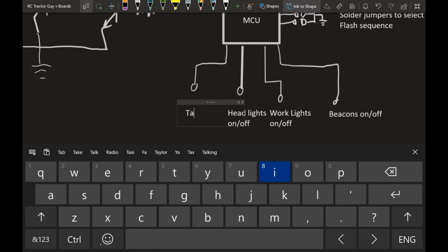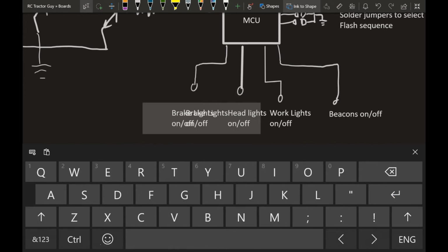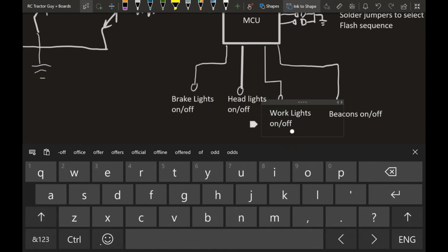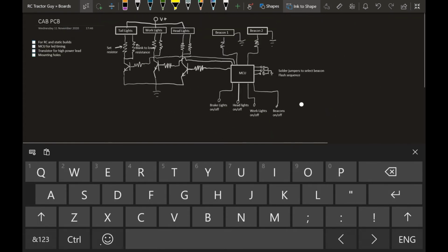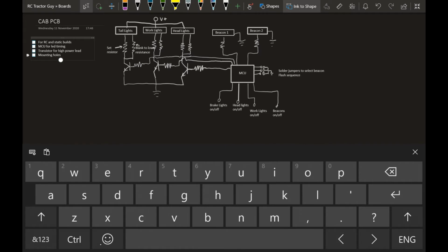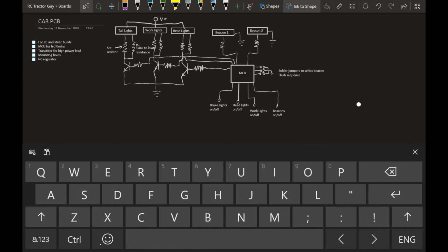It's around about this point that I decide that I'm not going to use a regulator on this circuit, so that'll mean we have to limit the upper voltage of our battery. But hopefully without the losses from a regulator, we'll be able to operate to a lower voltage without any difficulty. Maybe it would run okay on two AAA batteries, or maybe even on a coin cell.